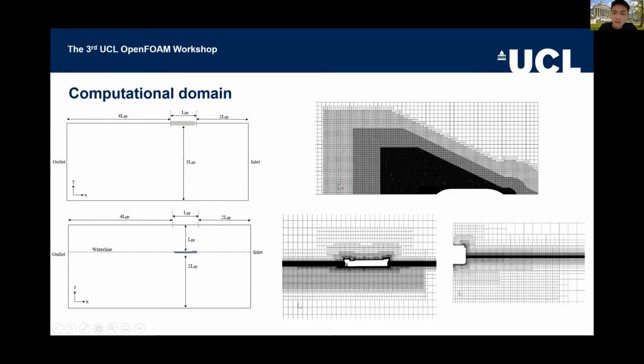Okay. So about the mesh part, in OpenFOAM, to solve any problem, you want to use as little mesh as possible, because you want to make the simulation as fast as possible, but remain accurate. This leads us to think that we only need to refine the mesh near the important part of the domain.